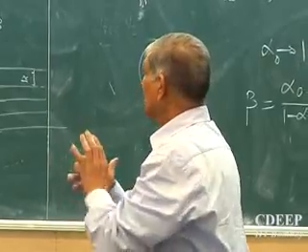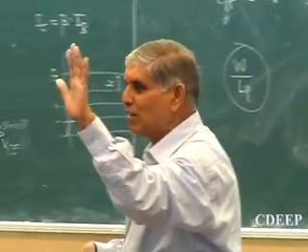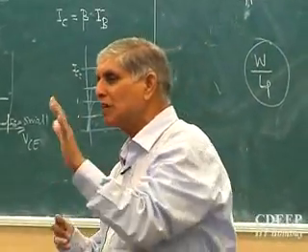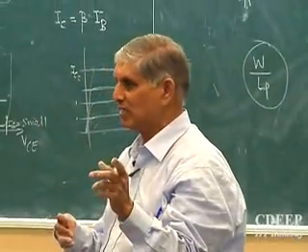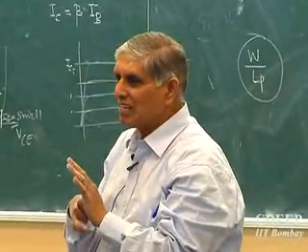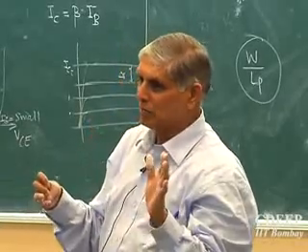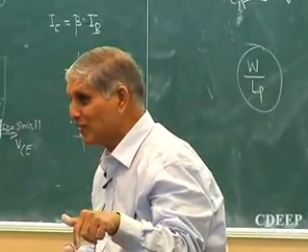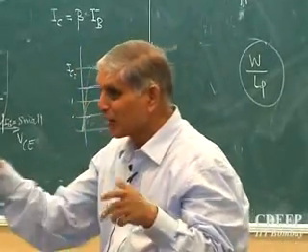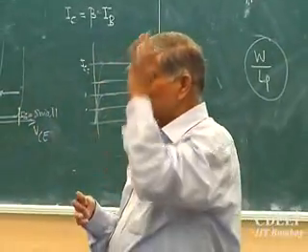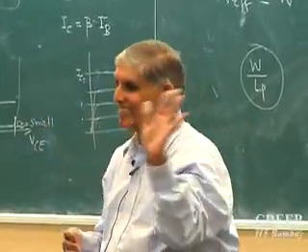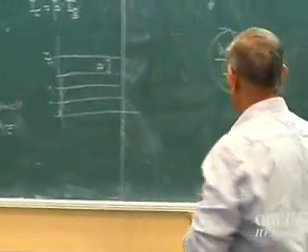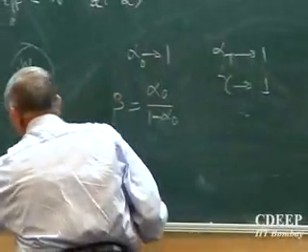In a circuit, never believe these manual values, because manual values are typical values. They are not for every device. Is that correct? Typical is neither max nor min, somewhere in between. So most of them. But which one you are using, you don't know. The minimum one or maximum, you don't know. So always keep the 70% safe side. Okay, so that never fails. So these are two.